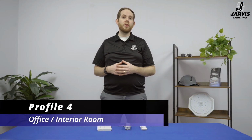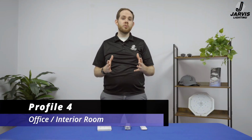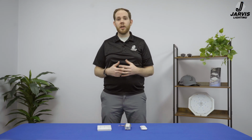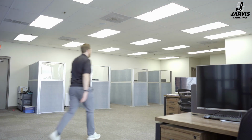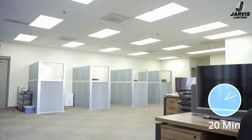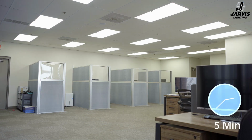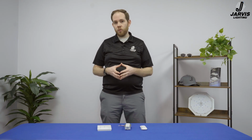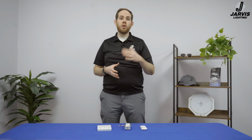Our fourth profile, the Office Interior Room profile, is best suited for smaller interior spaces such as offices and classrooms that are continuously occupied throughout the day. This profile can utilize just passive infrared sensors, or PIR sensors, or a combination of PIR sensors and wireless control modules, or WCMs. Fixtures in a zone assigned this profile will turn on at 100% when the PIR sensors detect motion, dim to 50% after 20 minutes of no motion detected, and turn off after an additional 5 minutes of no motion.